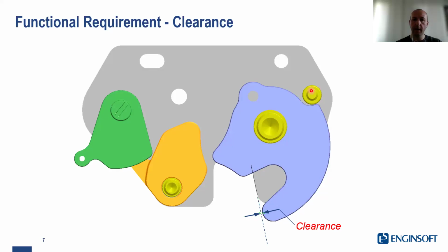my seat latch. And from the tolerance point of view, from the tolerance chain point of view, we are going to calculate this functional requirement. It is called the clearance. And we want to have the clearance always positive. So we want to study the tolerance propagation inside this three-dimensional product to understand which is the risk to have a negative clearance, because we don't want to have a negative clearance, otherwise our product requirement will be negative in this case.